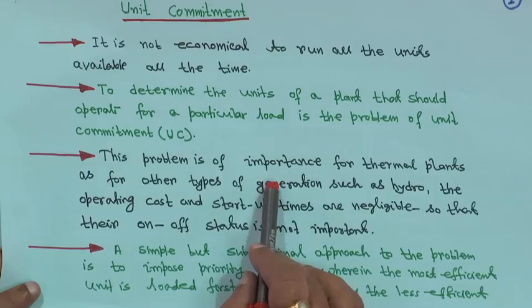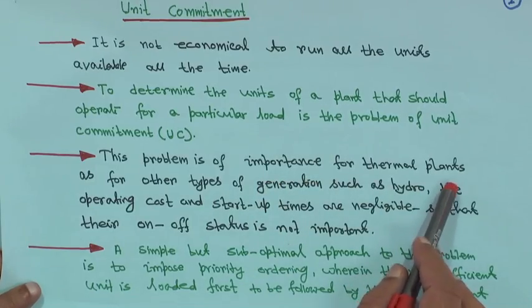It is because it is a huge dynamics, boiler is also involved, and boiler dynamics is very slow, right. Boilers, economizer, those dynamics are very slow, they take time, and a lot of non-linearities are involved also in that, what you call AGC. I did not tell those non-linearities, I have only mentioned them, right. I believe that for undergraduate level things are okay, but many constraints are there also, right, and security is another issue for unit commitment.